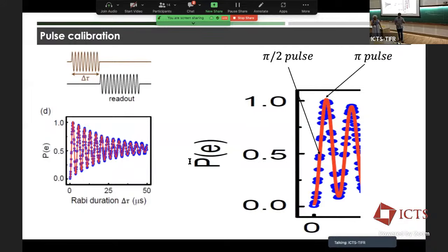You can still have quasi-particles coming in and out of your circuit, which can give rise to frequency fluctuations depending on the particular circuit. So all these different qubits are affected by these different processes by differing amounts. There are experiments which allow you to characterize which of the noises you seem to be more dominated by. And then over the years, people have tried to fix these issues by better shielding, using different materials to reduce the dielectric losses in two-level systems, and so on and so forth. That, at least for now, is one of the major